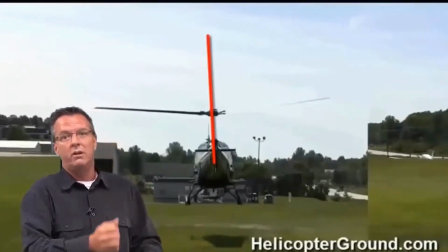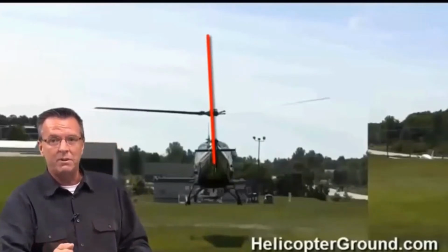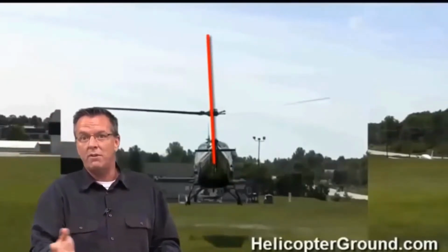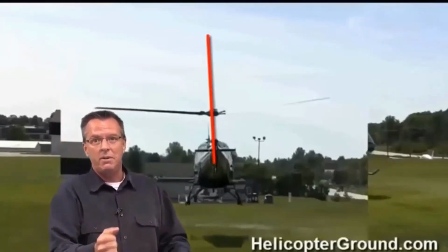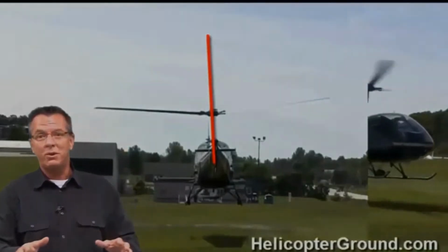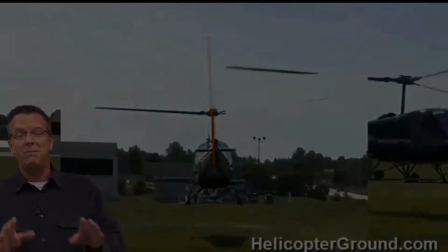Some aircraft have a change in their rigging to compensate for it. There are some aircraft that they don't compensate at all. You just hold the cyclic to keep the aircraft centered. So if you've struggled with this, don't feel bad. Everybody messes up the 3 T's.